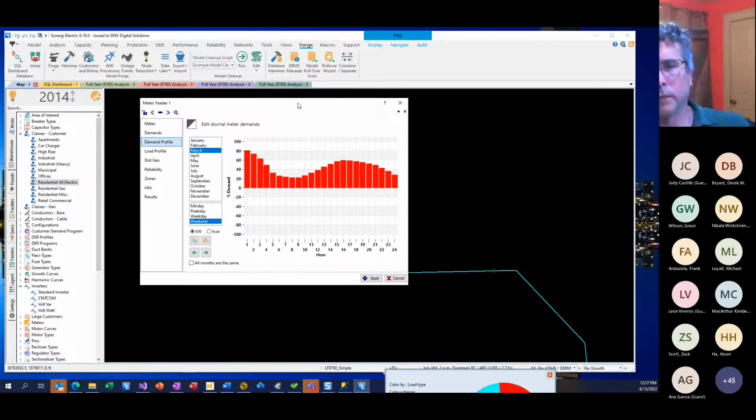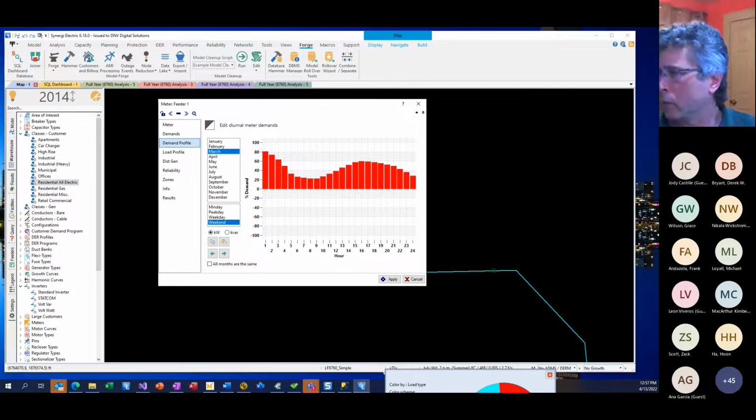There's capacitors and non-meter, there's all kinds of other stuff. So if we have demands at the feeder, we run a load flow and those demands don't match the load flow values, what can we do then to start truing those up and making things more consistent? That's some more stuff that we're going to work on. There are some tools for that now. We need to do more.